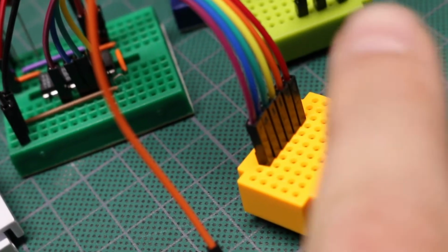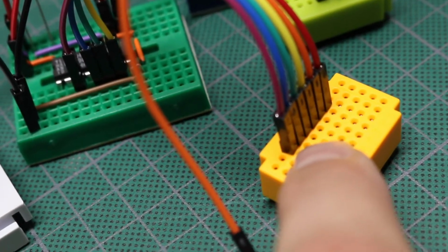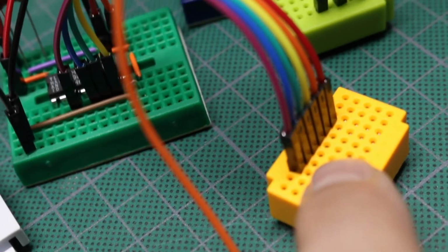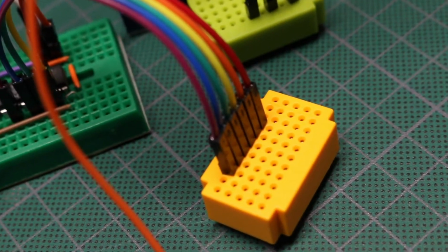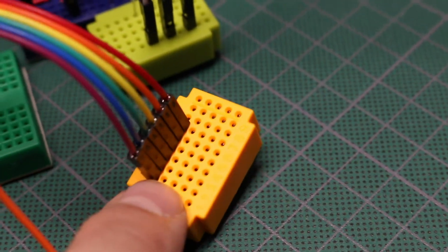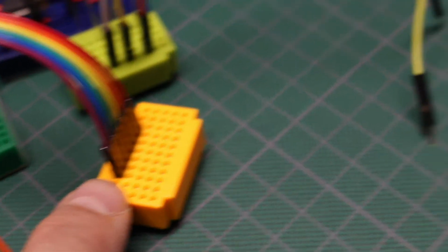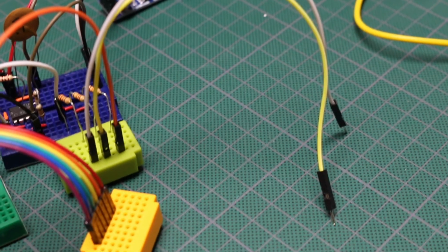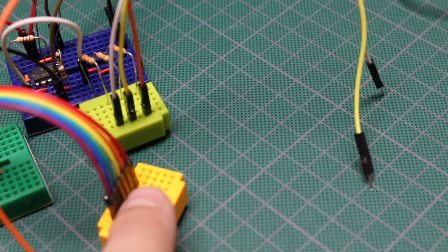So musically, each time an output is taken one step away from its neighbor, it changes by 1 octave. And then if you change the main frequency of the 555, everything changes by relative pitch. So it stays locked and still sounds musically intact. So the outputs of the 4040 are basically tone generators. So I have a couple of stray wires. I made 3 for now, so I could just move them between the outputs as I want.